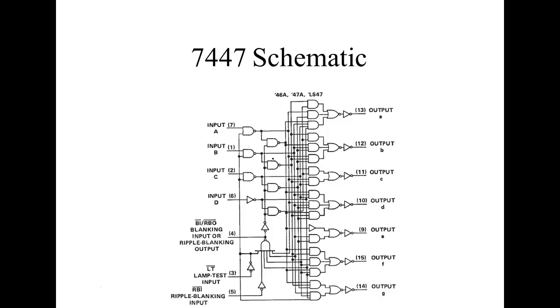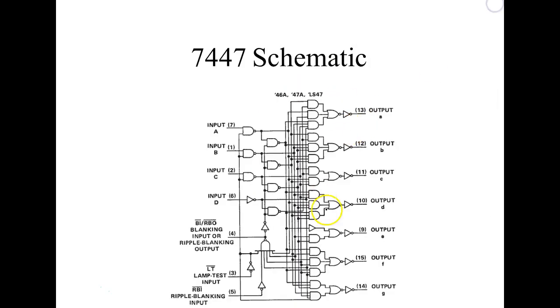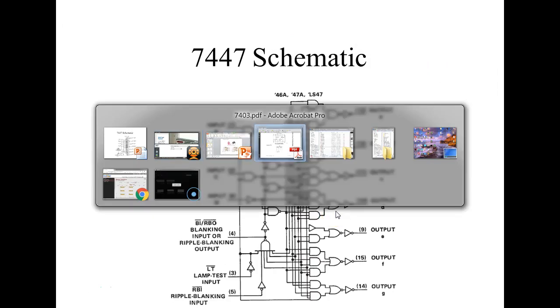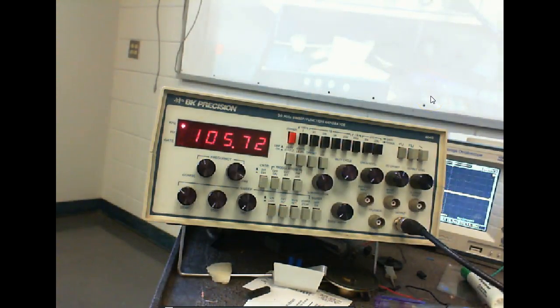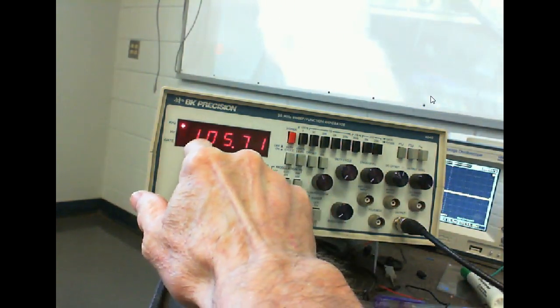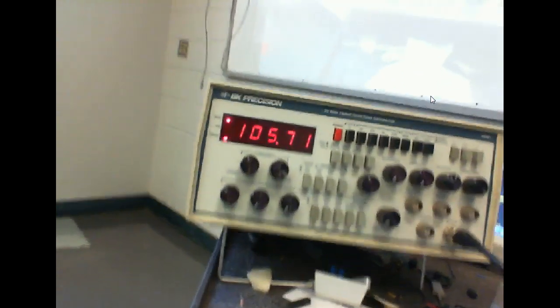So this guy right here, I'd almost bet if we got into this guy right here, it's blanking too, that guy, by the way. But I guarantee you, if we got into this guy right here, we'd either find a 7447 or a 7448, depending on what type of 7-segment display. So that's a 7-segment display right there. And here you can actually see the break in the lines.